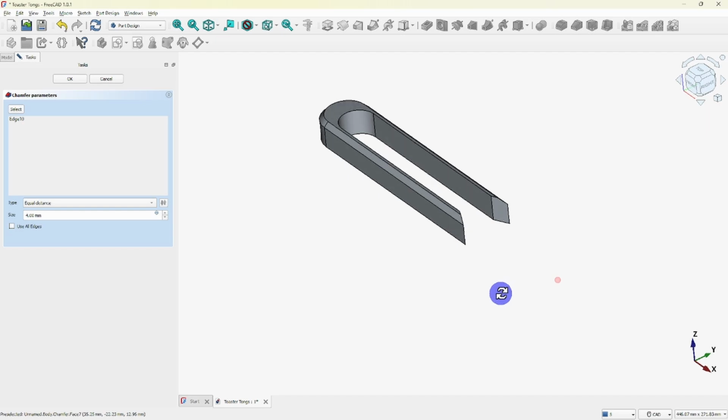Okay, and then if you keep increasing the chamfer, if the chamfer size gets larger than the thickness of your material, then it'll unchamfer it pictorially, and you created an error. So if I click this one more time, it's going to go up to 5 millimeters, and I don't know if that's going to mess up the chamfer or not. Let's try it. Oh, it allowed it.